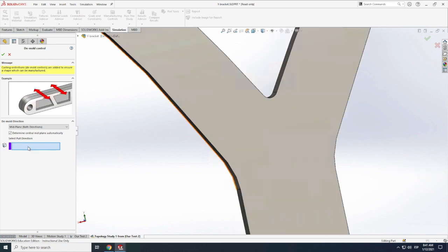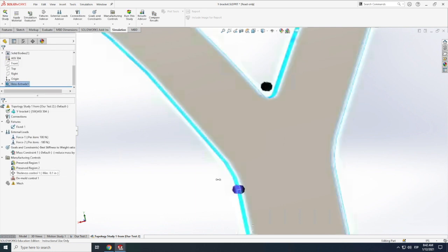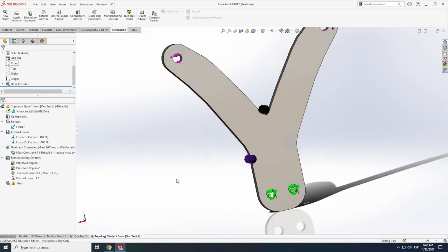In order to do that, we can select pull direction. From the tutorials I've seen before, generally the best practice would be to make it symmetrical. So it's mid-plane. I can choose that little edge over there, and these two arrows appear. Just click OK. It's just giving more flexibility to our final design. What else do we have? Let's specify a symmetry plane, but that is not necessary.